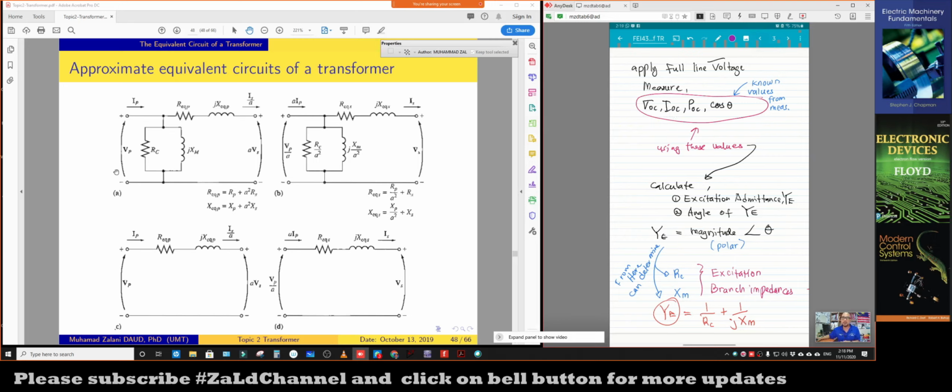That means we supply full voltage, meaning the voltage at the primary, for example if the voltage is 8000, we give that here. Then we measure the open circuit voltage, open circuit current, open circuit power, and the power factor. These we get from the experiment, and then we use these values to do the calculation.